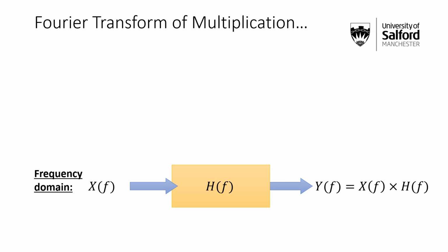So a little aside. We've been thinking about these systems where you put in a signal x, it passes through the system and you get an output signal y. We've talked about the fact that the response of a system can be a transfer function H, and that y is neatly represented as just x times H, so they're just multiplied. That's one of the reasons that transfer functions and complex numbers for representing spectra are really useful.